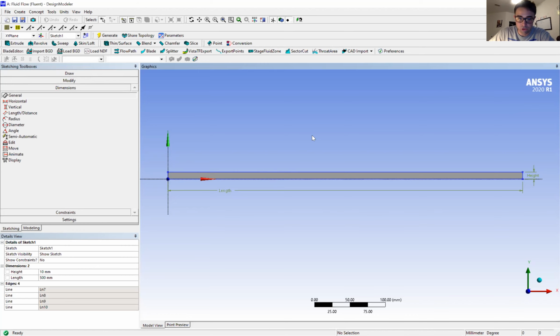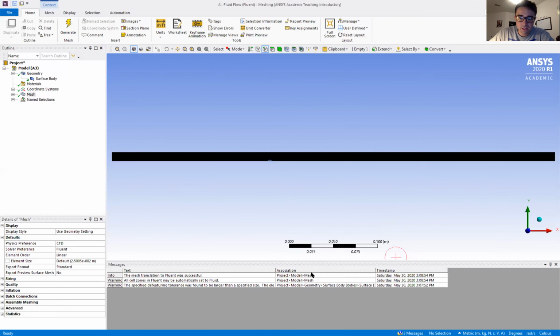Following this, the next portion is to do the meshing. Meshing is done by adding small divisions multiple times on each part of the figure to have a more refined figure when you complete the simulation. This is done by, if we go down to our mesh here, you start off by initializing the mesh with the automatic method. You then go down to edge sizing, which is where you basically choose your right and your left side edges, your inlet and your outlet. And you basically set a number of divisions for that.